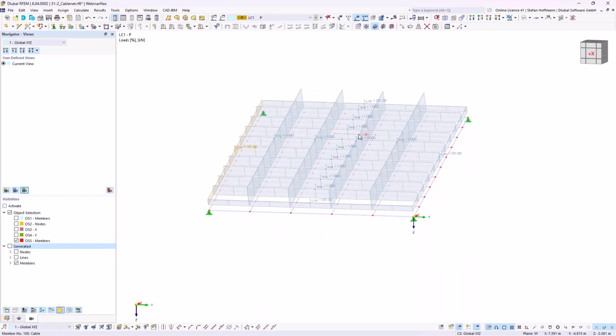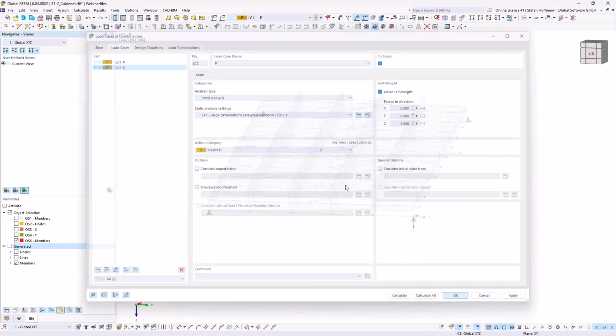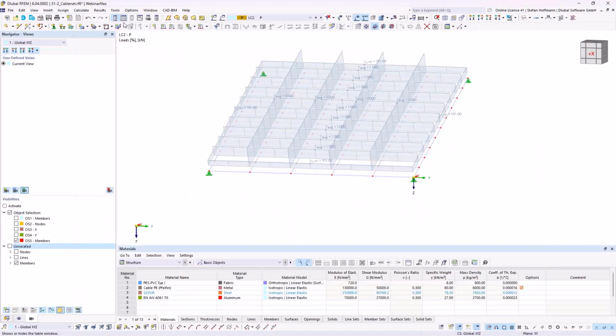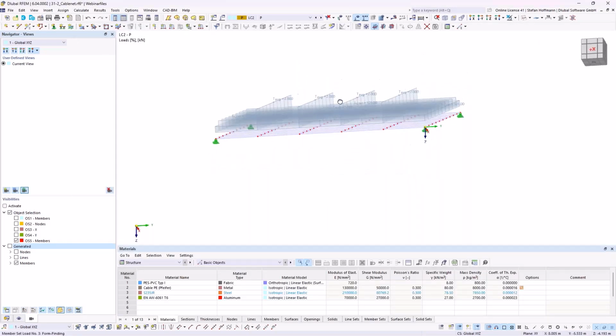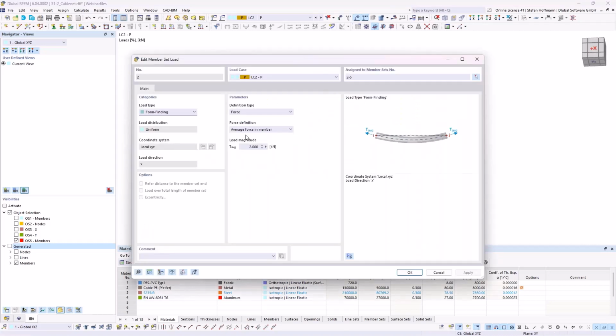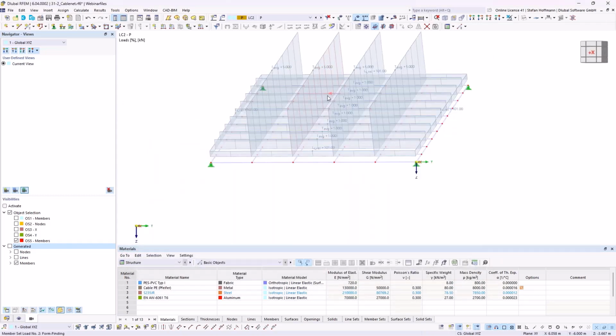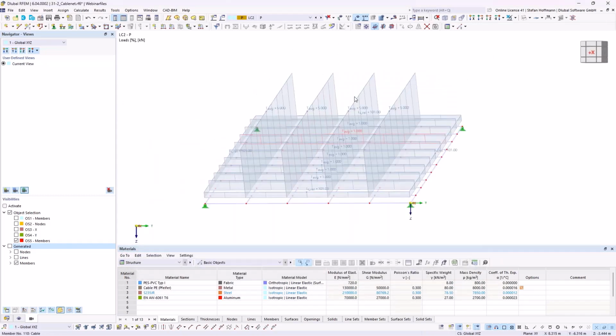And in the inner member forces, I have chosen 2 kilonewton in this direction, and in the Y direction, I have chosen 1. So remember, if you want to compare different pre-stresses in one file, you just simply have to copy this load case, for example. Then you can activate the table, or also just mark multiple forces over here in order to go in and quickly change it from 2 to 5. That's most likely all that has to be done.